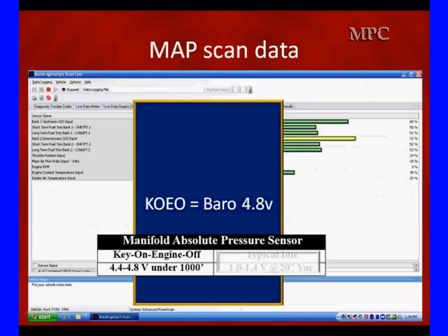Now, a word of caution. If your spec system doesn't show you tight specs like this, you can't rely on them. A lot of specs will read the same values that overlap between Long Beach and Denver, Colorado. If the 5,000 foot spec overlaps with the sea level spec, any at all, you cannot rely on them for effective testing. They still can be wrong. What we're trying to determine is if we start at zero vacuum, or full manifold pressure, barometric pressure, we're going to wind up with a reasonable voltage.